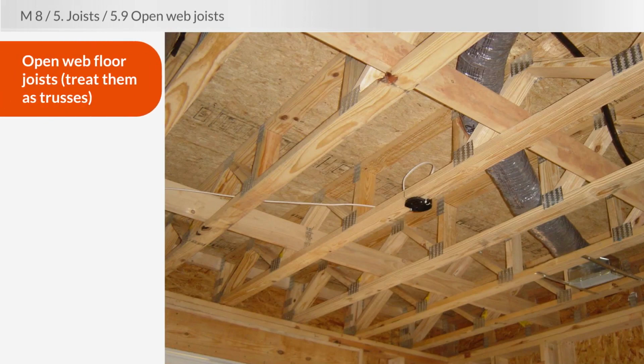These are open web floor joists. They really are trusses. These are hard to look at. When you're crawling through a crawl space or even in a basement, there's an awful lot of pieces to look at. And if even one of these pieces, if any one of the web pieces have been removed, that's a defect you should be finding and reporting and recommending further evaluation by structural engineers. So you really have to take your time with these. I absolutely hate looking at these because it's just very time-consuming.